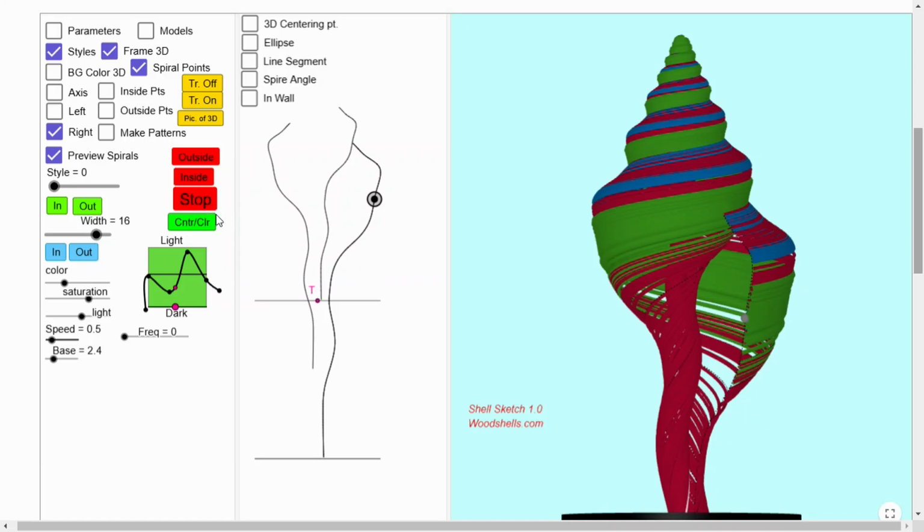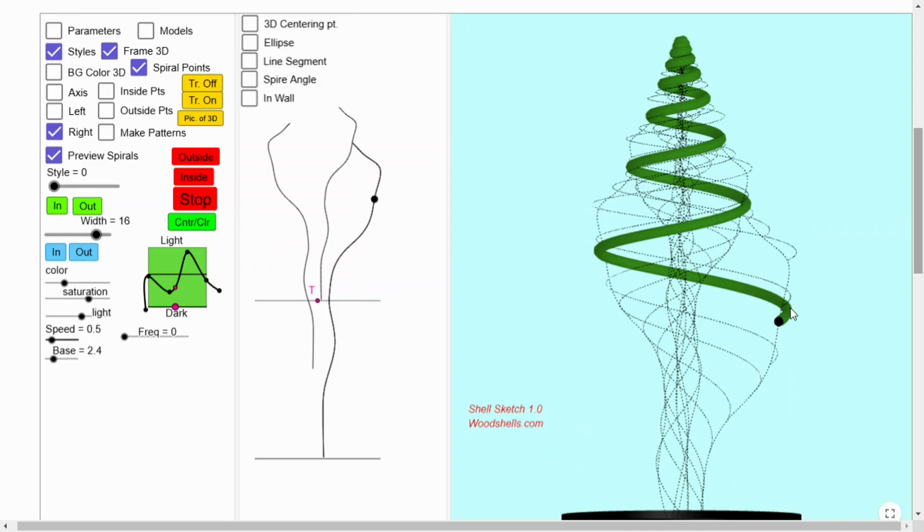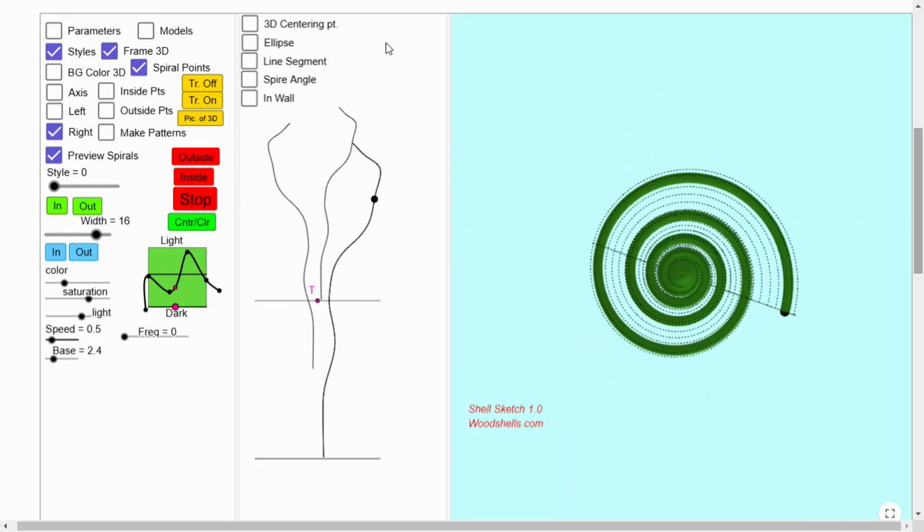And what else can I show you? Yeah, there's a much fatter line right there. You can go into parameters and change the curvature. This value right here, D, if it's set at 0, it won't have any spiraling. Everything will just be a circle. It's like, you know, as if you turned it on a lathe. And that slider, it's real slow to respond, so I'll just click on this input box and type in the number that I want.